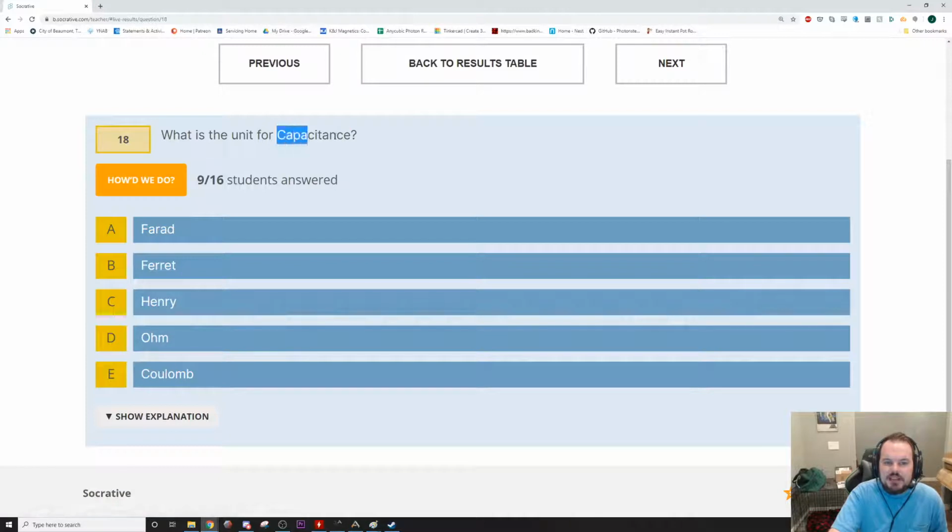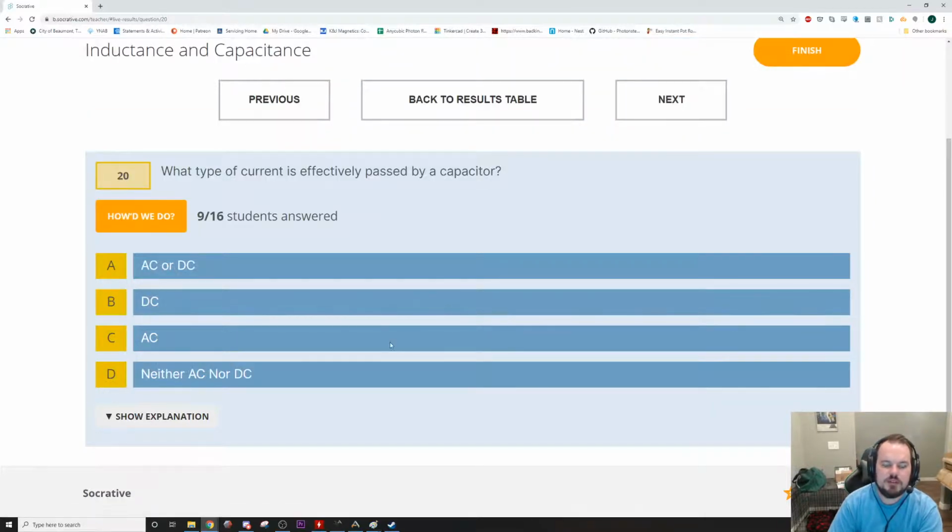So capacitance is the only thing that's different out of all of this. Capacitance in series calculates like resistance in parallel, and capacitance in parallel calculates just like resistance in series. But we'll see some formulas and calculations based on that.